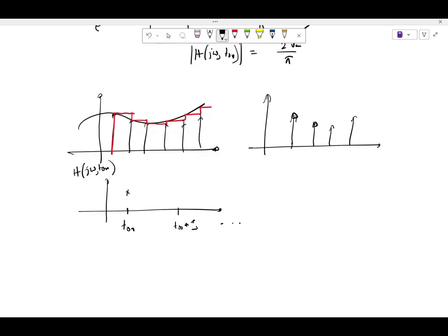I have sampled these values, whatever they are, right? And then we are saying that because the RC time constant is much, much higher than T on, these values are not going to change over that entire cycle. It's going to hold on to that value. It's an approximation, but that's what we are saying.